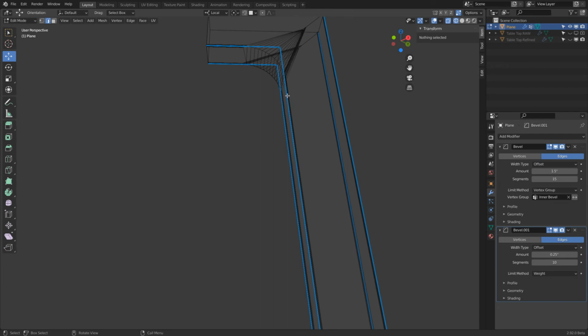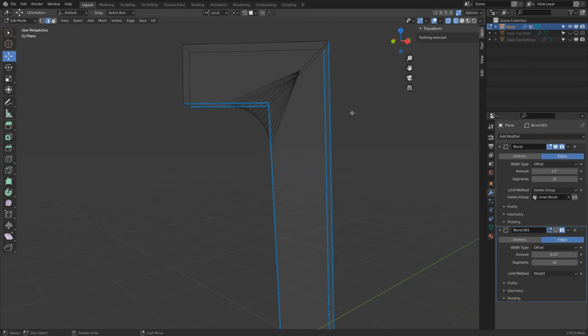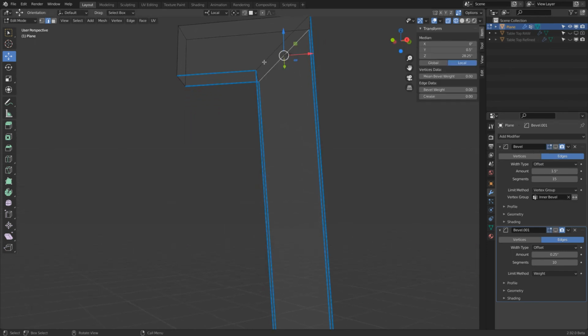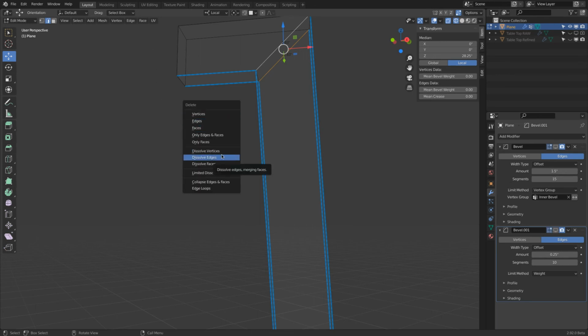You see how the fillet here goes onto the surface. So we need to help the program a little bit. And we do this by selecting this and this edge, and then we press X, delete, and say dissolve. So what's the difference between delete and dissolve? Delete really removes, think of it like cutting it open.